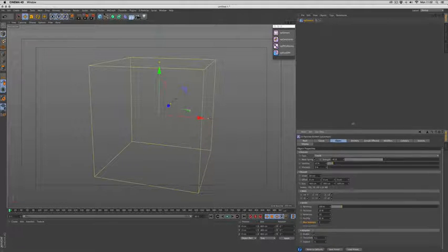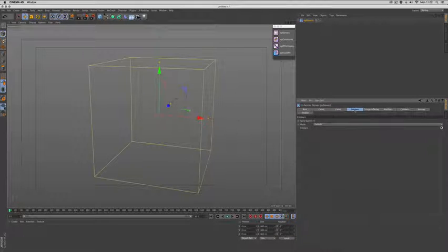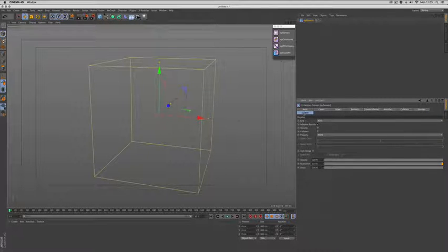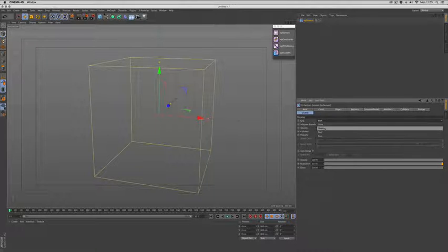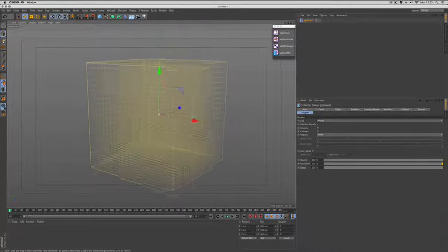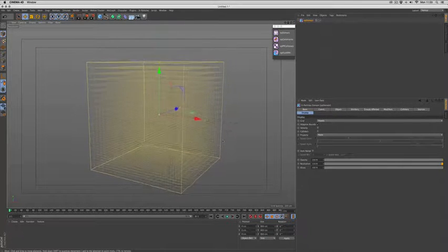We have tabs for exclusions such as emitters. We have a groups tag for groups within the modifiers. We have modifiers to be excluded and colliders to be excluded. Source objects as well. Then we have a tab for display. The display gives you options to look at things like the voxels. So you can see all the voxels inside the grid, and this is a good way to see if any collision objects are going to leak and how your sim is working.